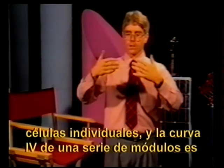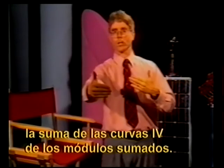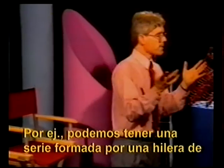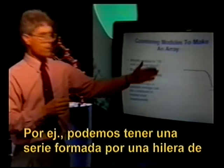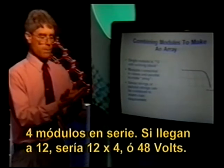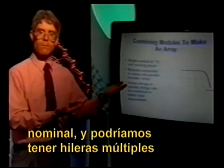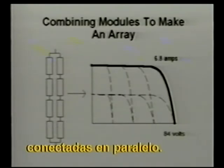And the IV curve of an array of modules is just the sum of the IV curves of the modules added together. For example, we could have an array made up of a string of 4 modules in series. If these are each 12-volt modules, that would be 12 times 4, or 48 volts nominal. And we could have multiple strings connected in parallel.